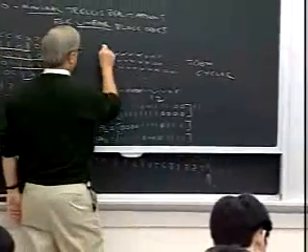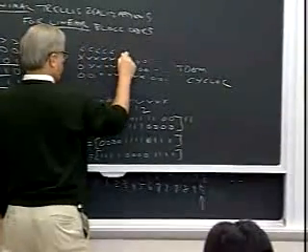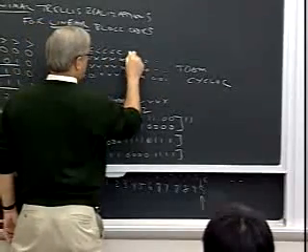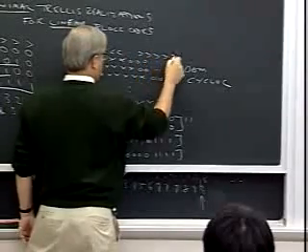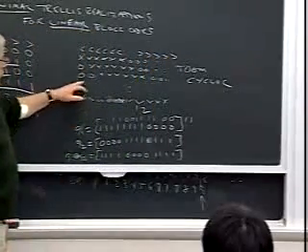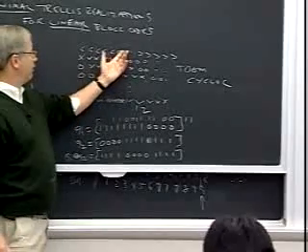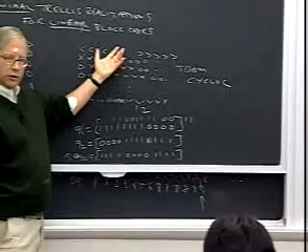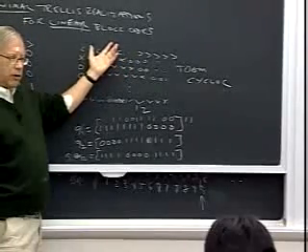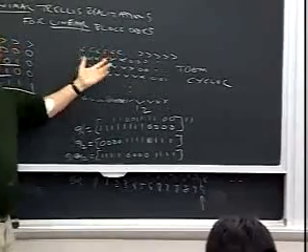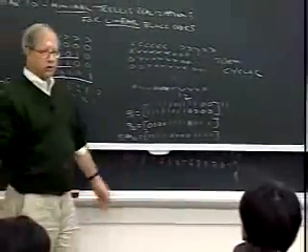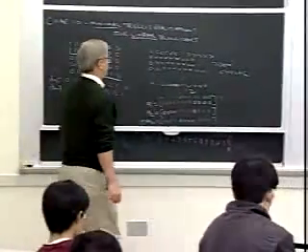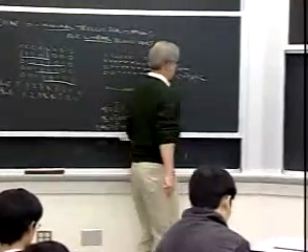And it's always going to have this worst case. All the branch diverges are going to occur over here. Then you may get nothing for a while, and then all the merges over here, which, if it's a rate less than 1/2 code, this means that the trellis complexity is basically going to be 2 to the k. Or if it's a high rate code, it means it's going to be 2 to the n minus k. And again, you get no improvement over simple exhaustive minimum distance decoding, or maximum likelihood decoding. So cyclic is very bad from a trellis point of view.